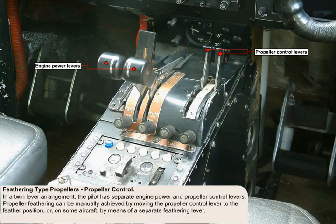The controls available to the pilot are again dependent on type. Most spark ignition piston engines and many turboprop engines are equipped with a twin-lever cockpit arrangement, whereby the pilot has separate engine power and propeller control levers. In this arrangement, propeller feathering can be manually achieved by moving the propeller control lever to the feather position, or on some aircraft by means of a separate feather lever.